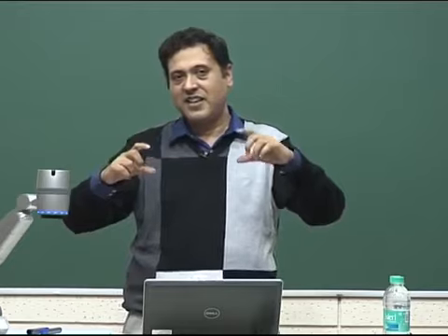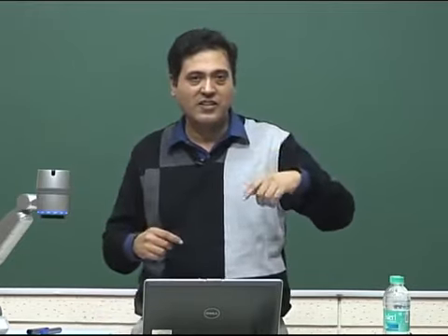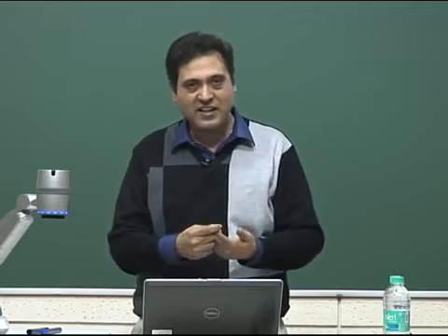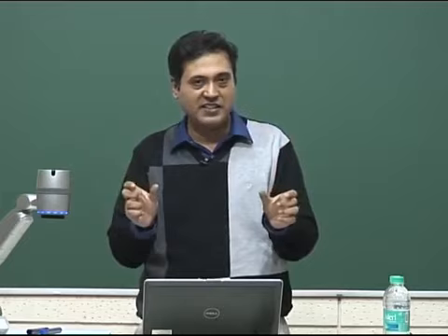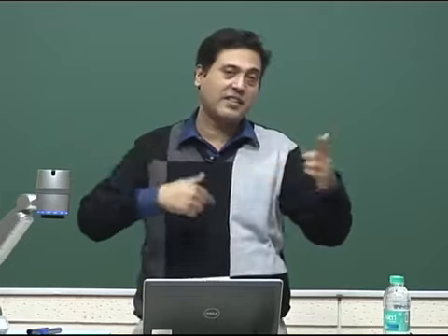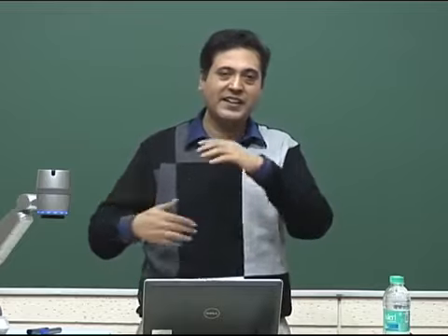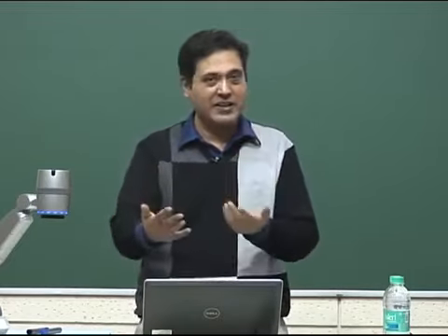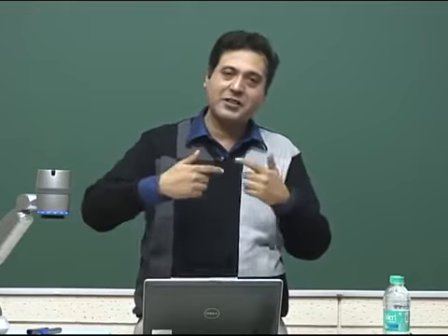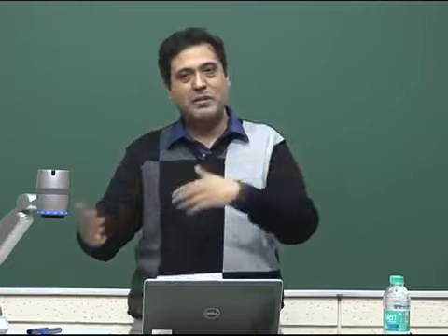So inside the sensor there are 2 cores. It's working on the air coil. It's not having a metallic core inside it. It's just a coil with an air gap inside, and there are two coils inside the sensor. One coil is providing the field, the second coil is acting as a compensation. So, in case of the target, the eddy currents which are produced, the oscillations being of the same magnitude, it compensates that.